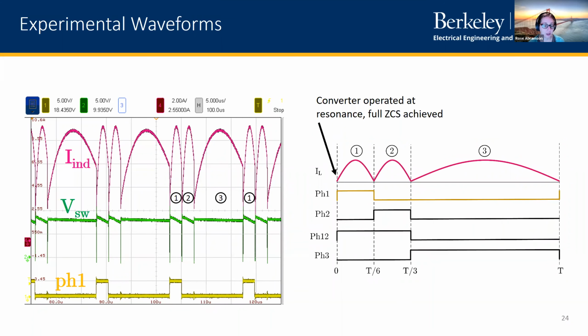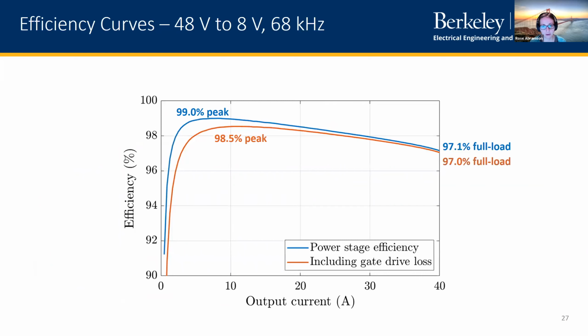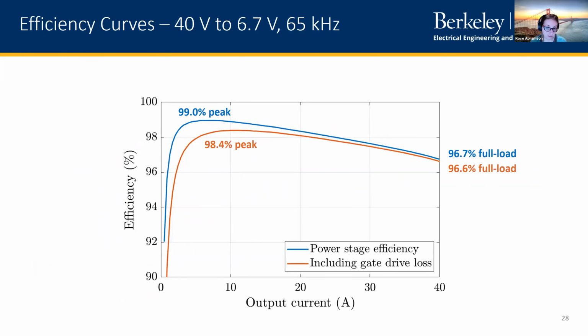We do tune the efficiency, as you can see at the various operating input voltages. We've slightly changed the switching frequency, and that's just based on manually sweeping through and seeing what is most efficient. But it's not something where we really care or have to track it.